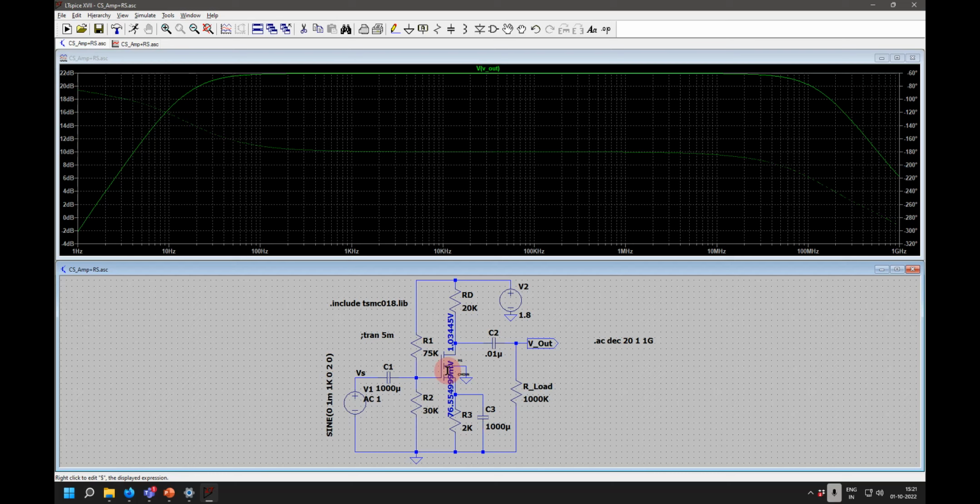So we generally change the topology in case we want a high frequency amplifier. Instead of going for a CS amplifier, we might go for a Cascode amplifier or a CG amplifier. That way, only the low frequency capacitances we take into consideration.